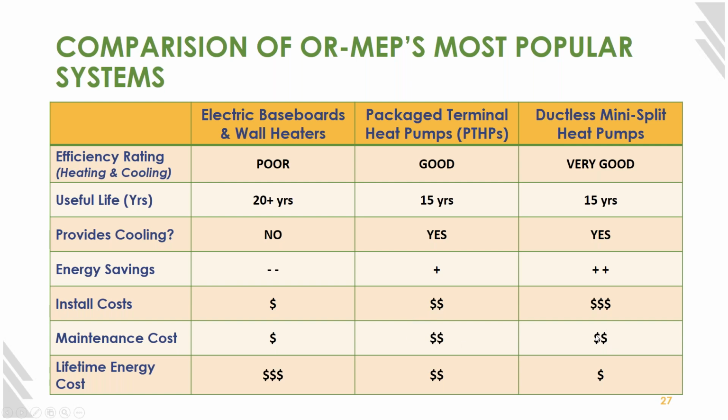In some cases, they will all have a condensate drain. In some cases, if they're not able to drain that via gravity and slope, they may include a condensate pump to get the condensate out. That's another moving part that can break, so there is maintenance and upkeep associated with that.